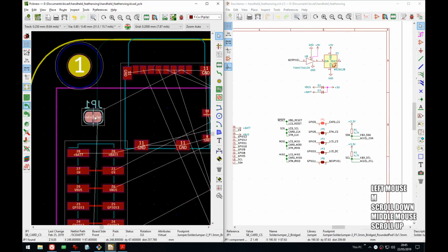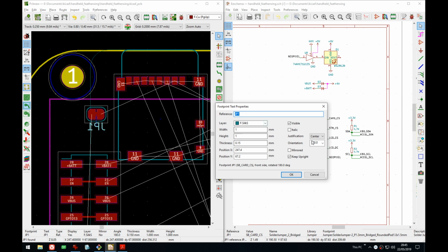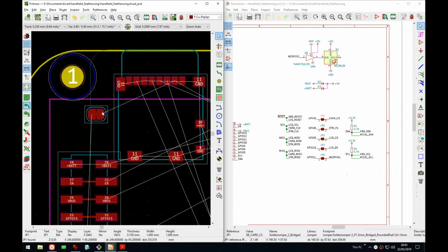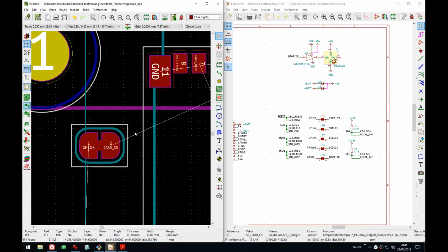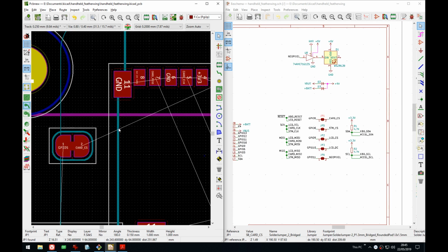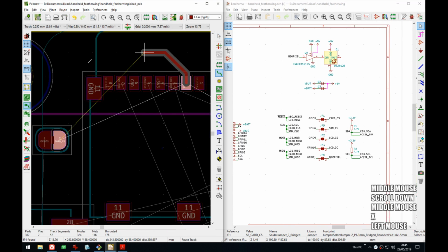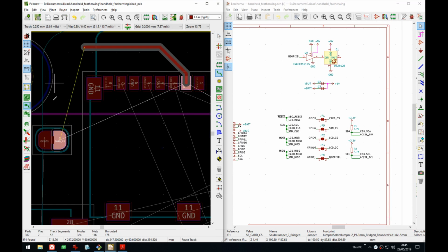I'm quite happy that KiCad finally added a footprint for solder bridges. Way back when I first started using KiCad, you had to make your own, and I mean, it was only a one-time thing, but still it was non-standard. Now they have their own, so that's nice. And they have normally open, normally closed, and a triple where you can do 1 and 2 or 2 and 3. That's kind of cool. So that's quite nice of them.